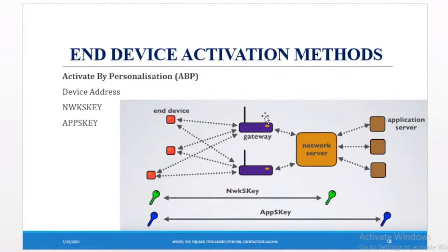But in OTAA mode, instead of this direct device address, it is using EUIs. For every join request, that device address will differ.